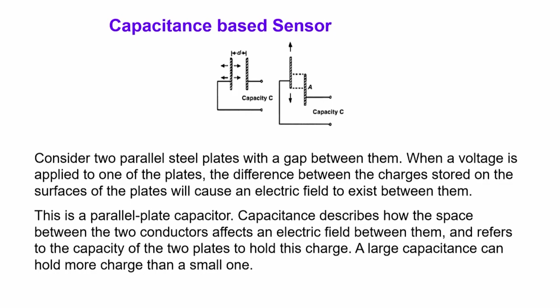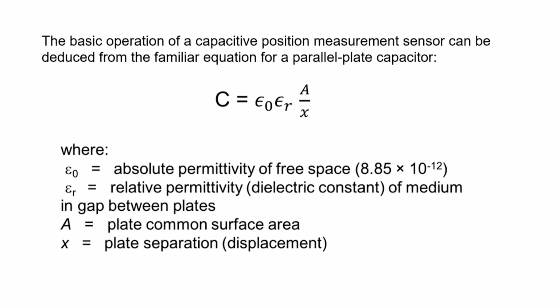Now, another system that is used for short distance movement is called the capacitance based sensor. In this case, there are two things that you can measure. One is the distance between the capacitor plates, which is d, and another is the overlapping distance between the two plates. If we can measure both of them together, then we should be able to predict in which direction the system is going to move, and the motion would be generated.